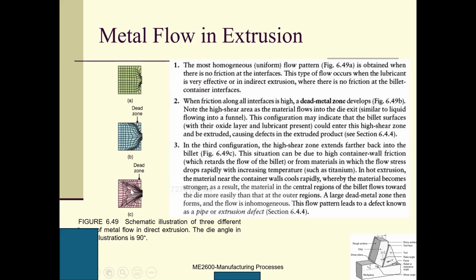Two reasons, right? First reason, a high frictional coefficient between the material and the wall. Second, because near the wall the temperature is lower than the temperature in the middle. As a result, the material in the center will move faster than the material near the wall. So these two reasons give us this longer dead zone. This is intuitive. If you have difficulty understanding this, we can talk further. Good.